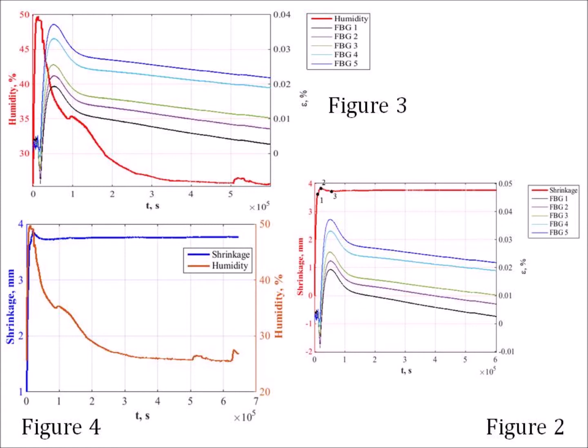The free surface of the sample at this stage begins to harden. Water, which has not yet entered an exothermic reaction and does not participate in the hydration of the concrete mixture, ceases to evaporate. This is confirmed by measurements performed by the humidity sensor in the experimental stand, whose data begins to drop, while the temperature sensor data, on the contrary, rises. The second stage of shrinkage of the mixture begins.